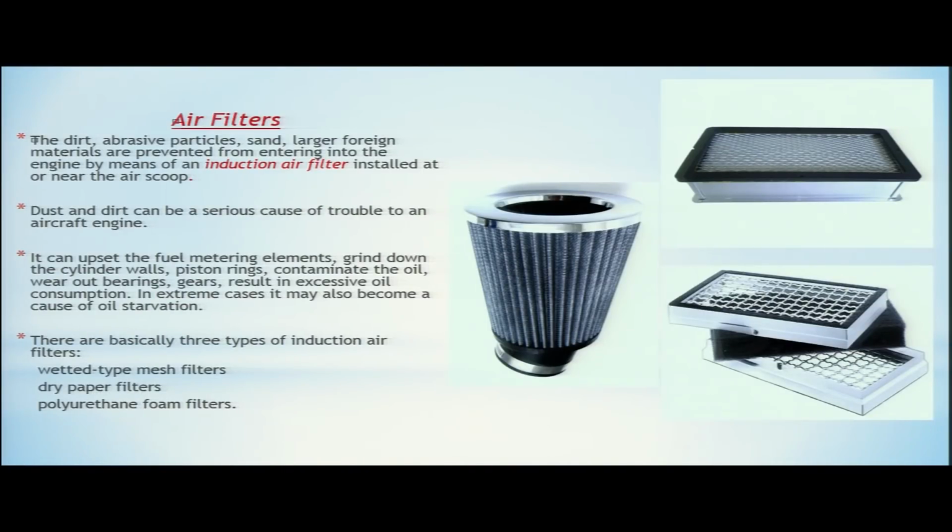It can contaminate the oil. You can imagine the lubricating oil inside the engine, if contaminated with dust and dirt, will harm all the moving parts in the engine. It can wear out the bearings and the gears, and can finally result in excessive oil consumption. In extreme cases, it may also become a cause of oil starvation.